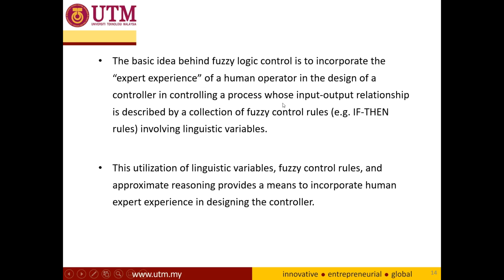in controlling a process whose input-output relationship is described by a collection of fuzzy control rules, for example, if-then rules involving linguistic variables. This utilization of linguistic variables, fuzzy control rules, and approximate reasoning provides a means to incorporate human expert experience in designing the controller. So I would say this will be the main uniqueness or advantage of the fuzzy logic controller, where we can include human expert experience in the form of fuzzy control rules.